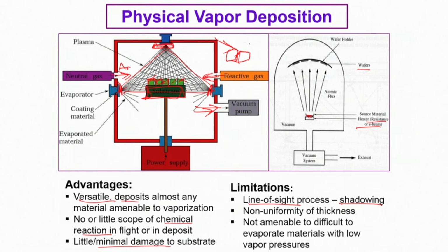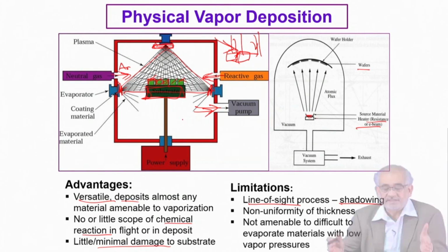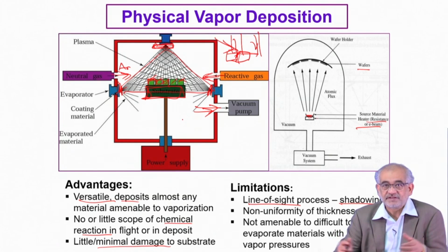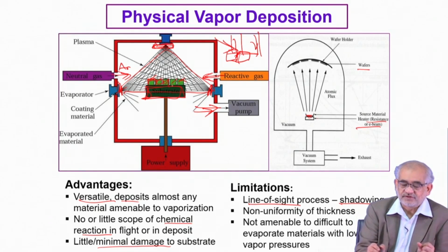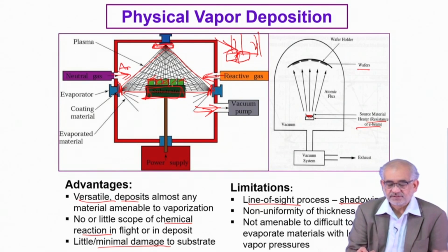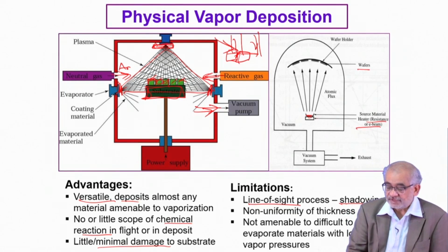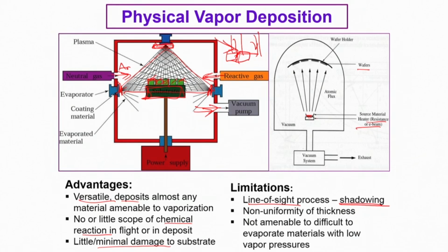So we have to make sure that the vapor arrives uniformly from the top or from one of the sides so that it can cover the entire area. In fact, the area of the vapor should be wider than the components that we are coating. Then we can make sure that the component is very uniformly covered. So we have to avoid this possible shadowing effect.